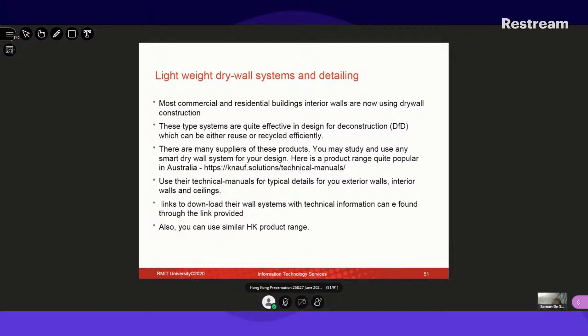And the most important thing now is that although a tall building is constructed, say for example for an office environment, the client will change in a few years, and some company or some individual or a developer will come and buy it, and they will also remove all the interior non-load bearing stuff, leaving the load bearing members only, and then they will retrofit or refit it completely differently. So for that reason, drywall construction has become very popular.